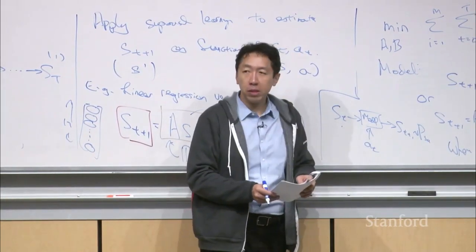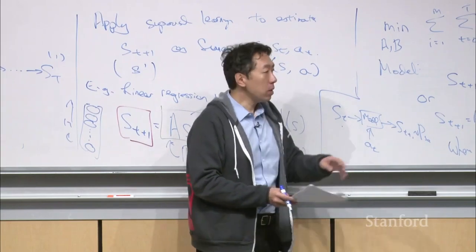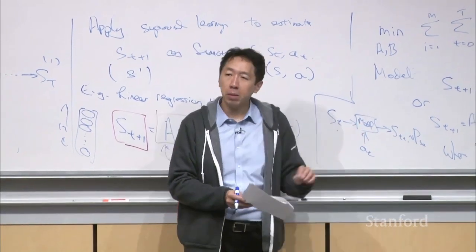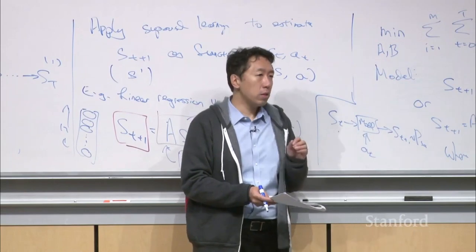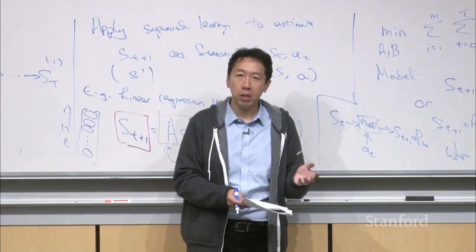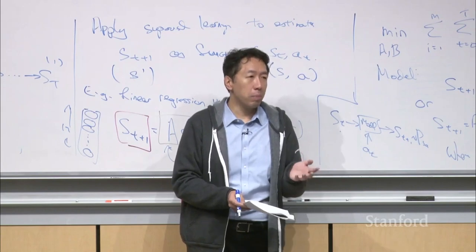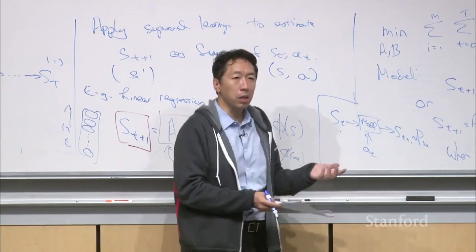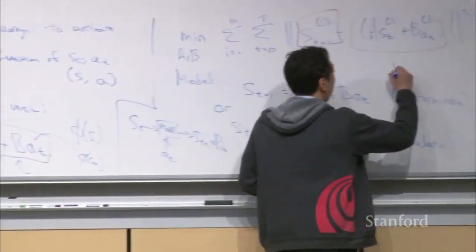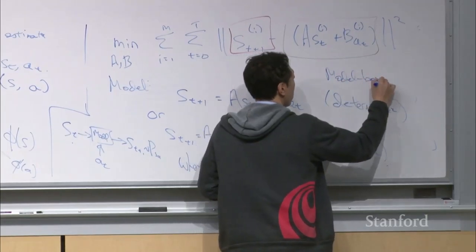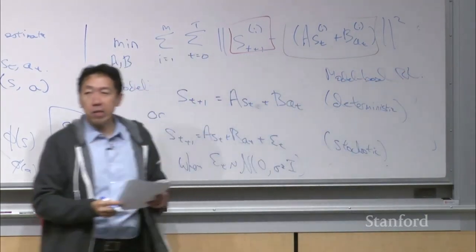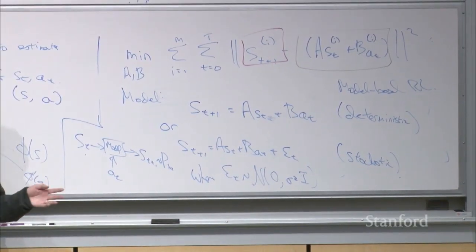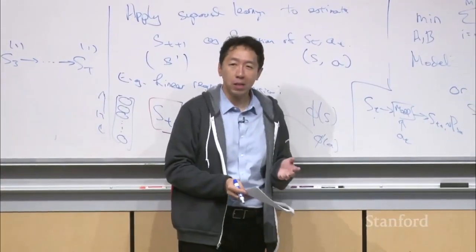In most cases, when you're building reinforcement learning models, the approach we're taking here is called model-based reinforcement learning, where you build a model of your robot, then train the reinforcement learning algorithm in the simulator, and then take the policy pi you learn in simulation and apply it back on your real robot. So this approach we're taking is called model-based RL. There's an alternative called model-free RL, which is where you just run your reinforcement learning algorithm on the robot directly and let the robot dash around and learn.